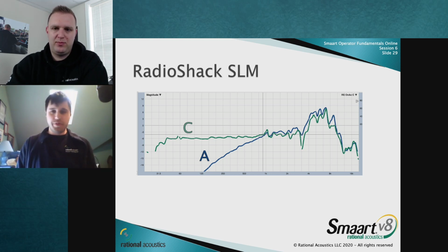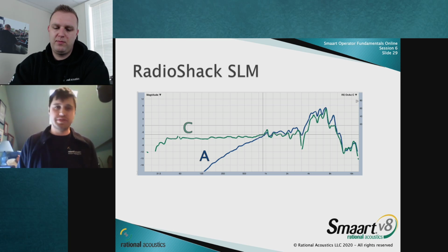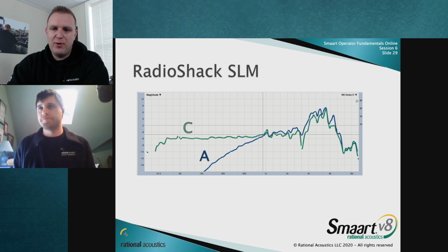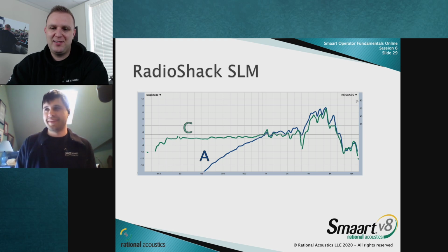So, you know, if you're using these things for relative measurements, a lot of these things live on the meter bridge of your mixing console. And again, you're just making sure you're hitting that same level every night. It's a great tool for that, but you want to be very careful about trusting what that number is telling you. I wouldn't want to make a legal decision, for example, based on that number. Yeah, it looks like we have about an octave wide 6 dB boost here at 6K or so. I wouldn't call that exactly flat. At least it's not in an important range, right?